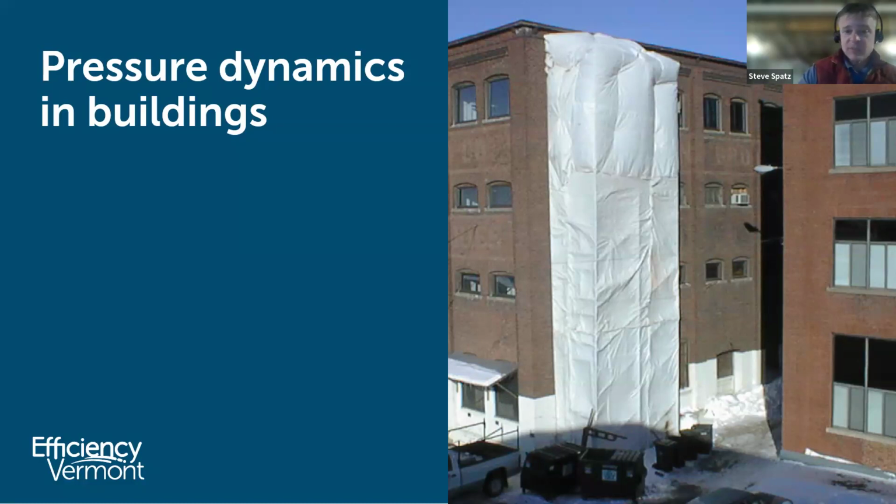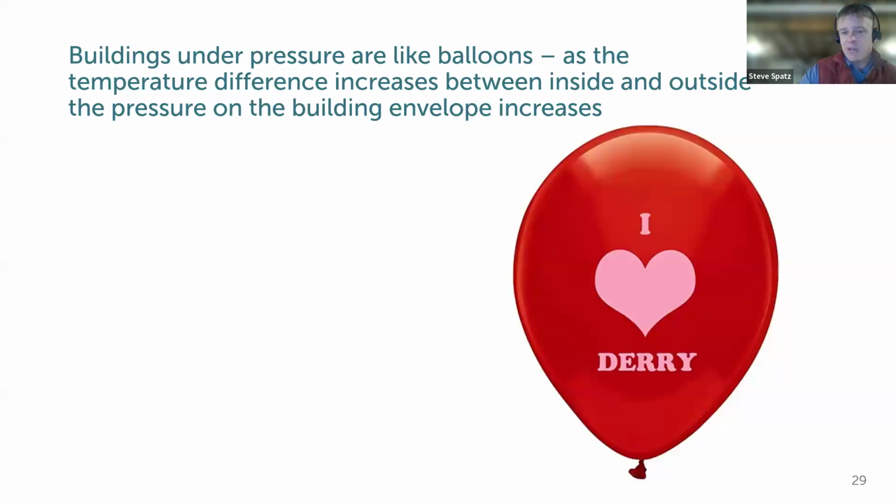So pressure dynamics in buildings. We're talking about physics at play here. And there are some fundamentals that we're not ever going to affect, so we just have to learn and know how to manage for them. Pressure dynamics exist within buildings due to a variety of different factors, but conceptually, the bigger the temperature difference between inside and outside is a primary driver of pressure differential. So the bigger the temperature differential between inside and outside, the more the pressure difference, and the more small pieces of the puzzle where potential leaks may be can be more impactful, because you think about a balloon and you poke a hole in it, moving that air out in short order through a small space.